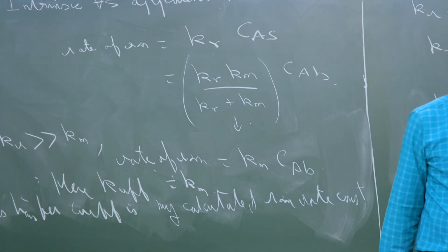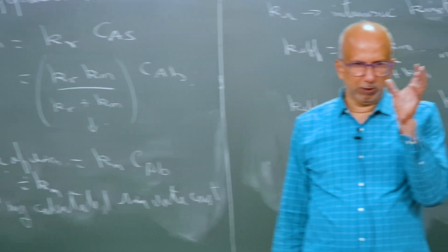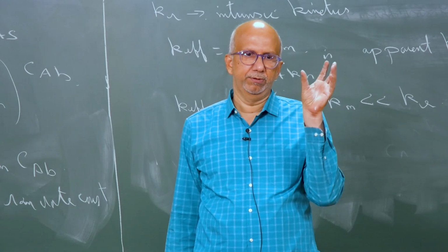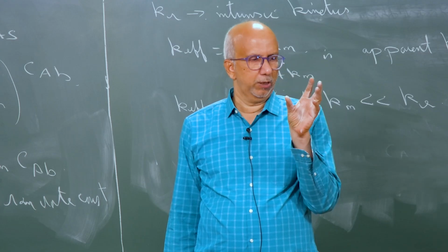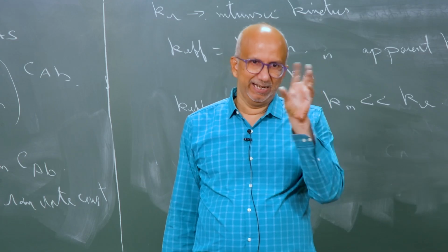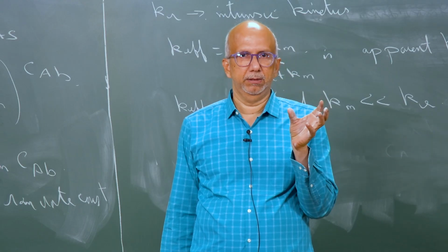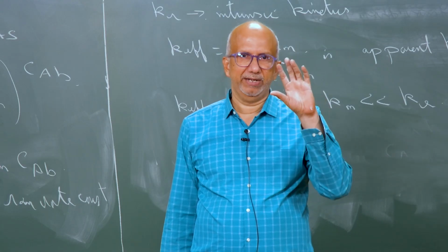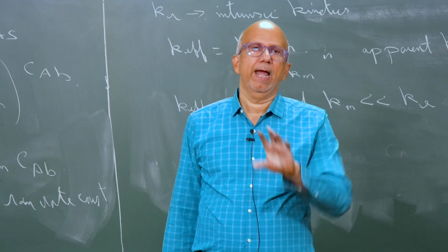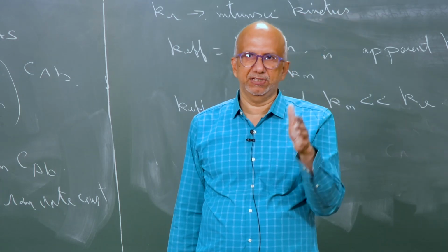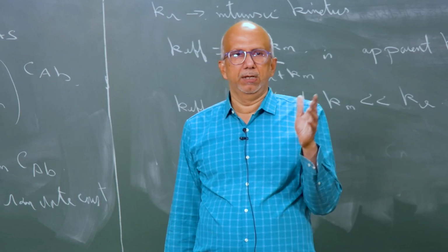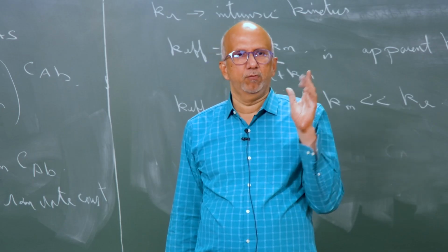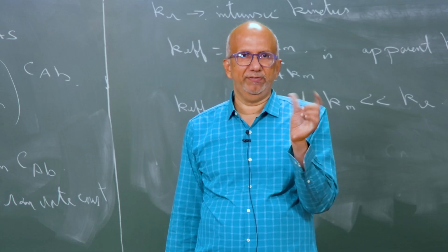Finally, I just want to say, in an actual pellet, if you have a porous pellet, you have the internal diffusional resistance inside the particle, inside the pellet, you have the reaction rate, and you have the external mass transfer resistance from the bulk to the surface. Now, what we have done is we have considered only two effects at a time.